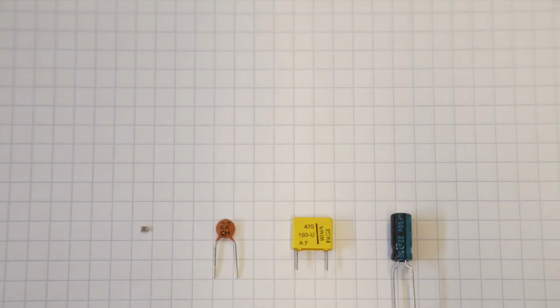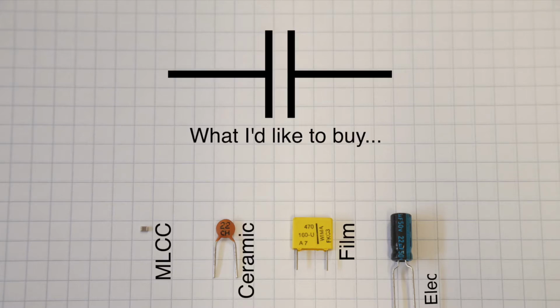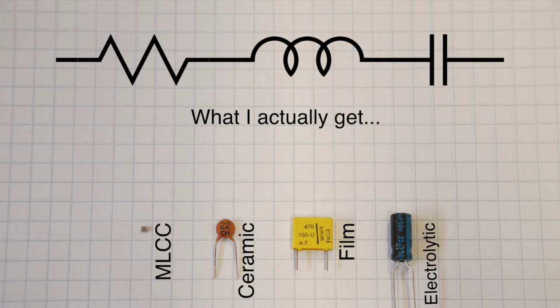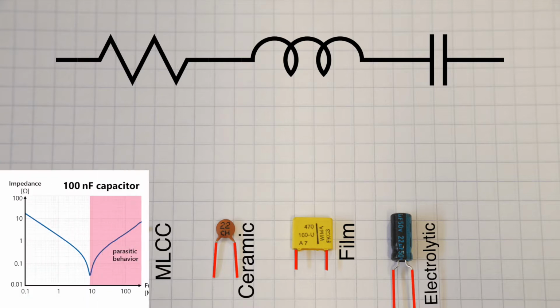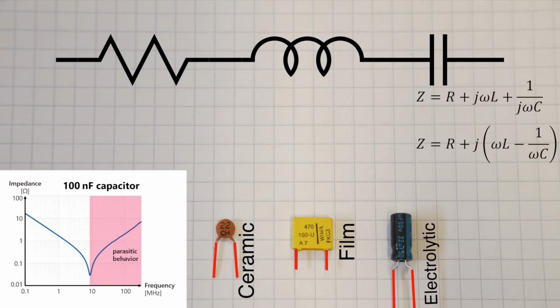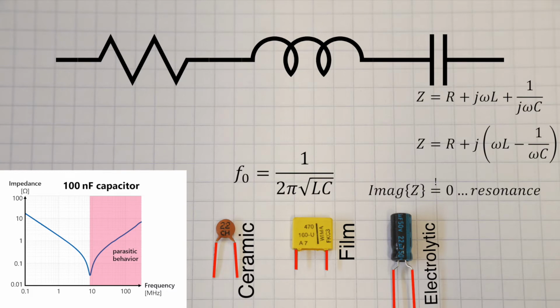Let's look at a simple example you can use a VNA for. When you buy a capacitor, you get an inductor for free. This parasitic element comes mainly from the connection wires. Thus, in reality, the capacitor is a series resonance circuit consisting of R, L and C. But can we also quantify the parasitic elements with numbers so that we can build a SPICE model out of them?